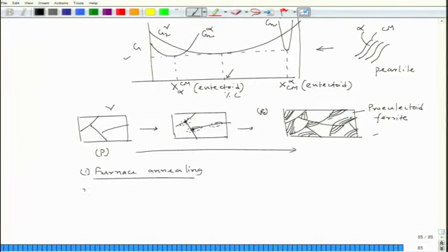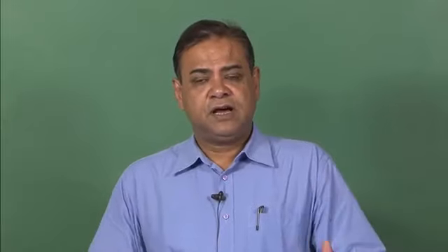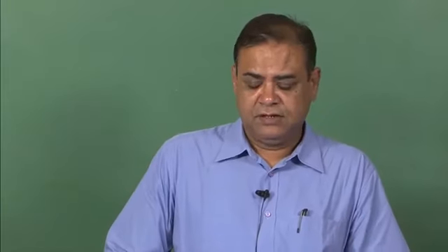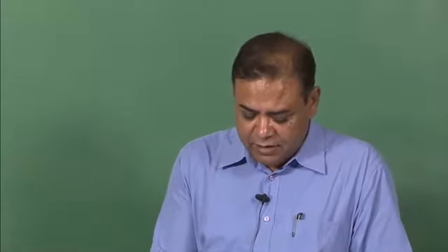But if I do the heat treatment, let us say I take it to austenitizing temperature, I convert everything into austenite, then I take the sample out and leave it in the air. So, when I take the sample out in the air, the cooling rate would be faster. So, that time we call it normalizing.